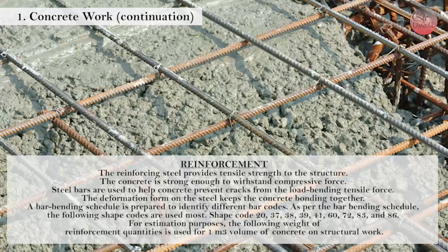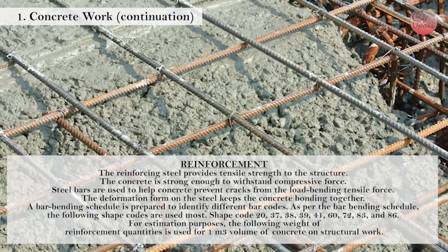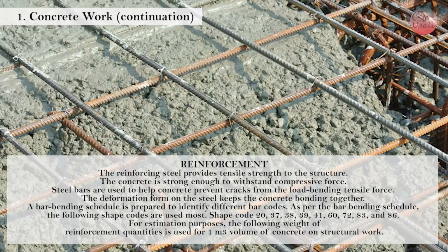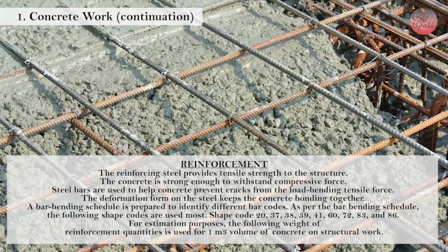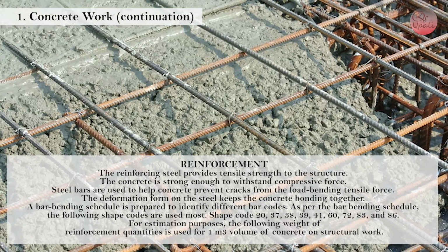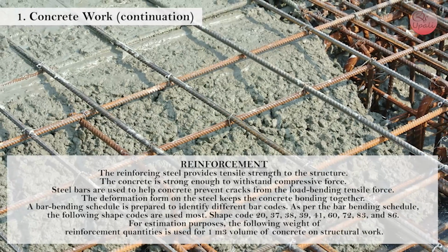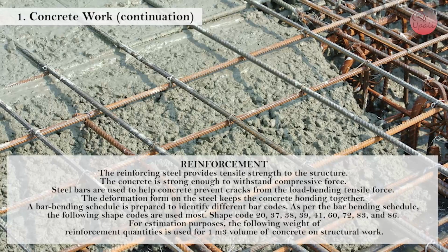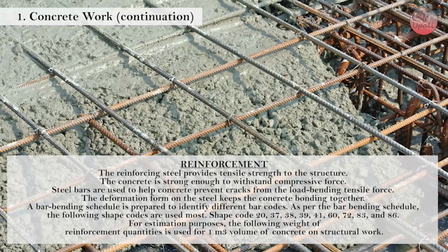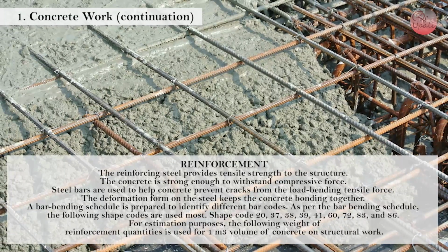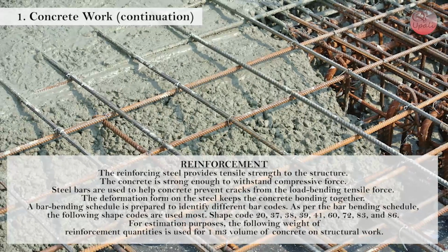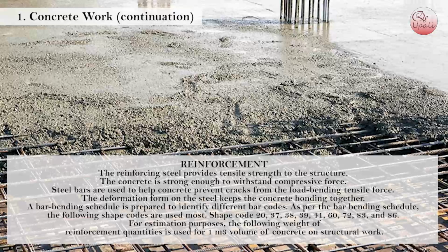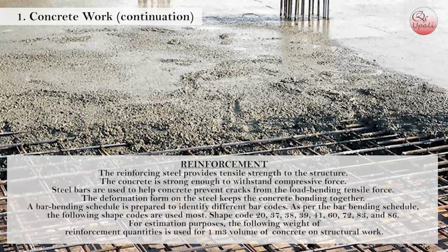1. Concrete work, continuation. Reinforcement. The reinforcing steel provides tensile strength to the structure. The concrete is strong enough to withstand compressive force. Steel bars are used to help concrete prevent cracks from the load bending tensile force. The deformation formed on the steel keeps the concrete bonding together.